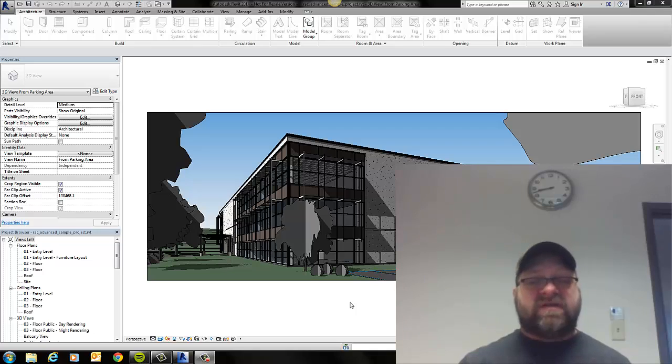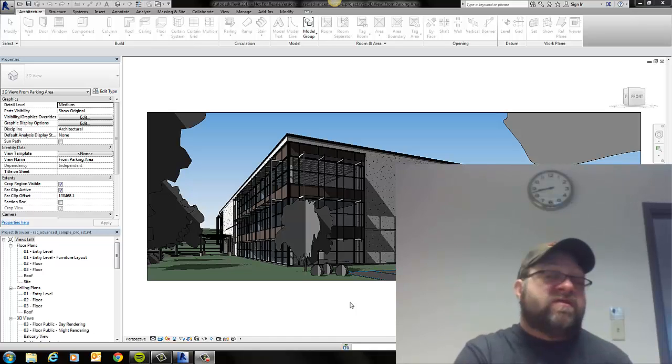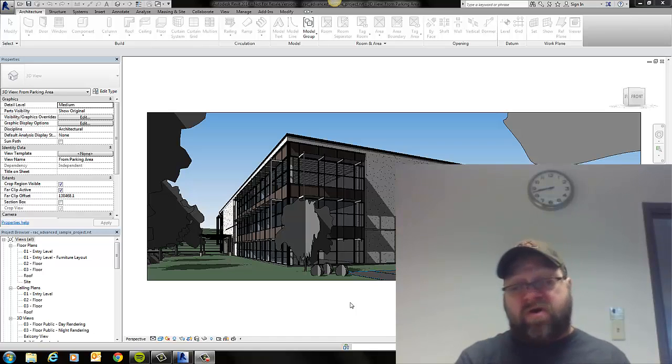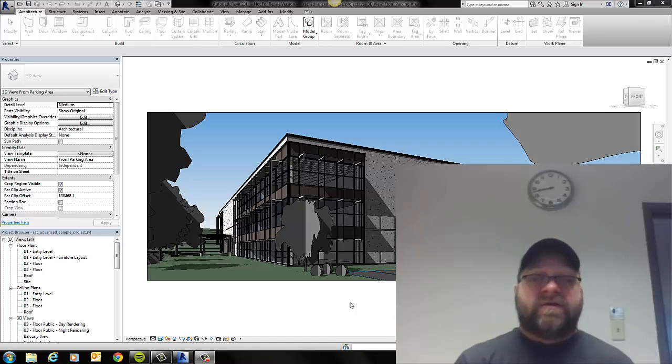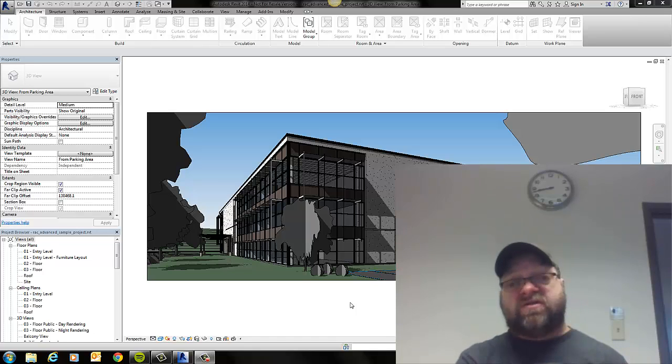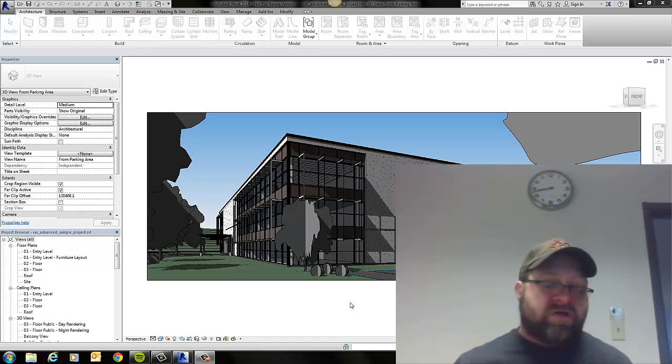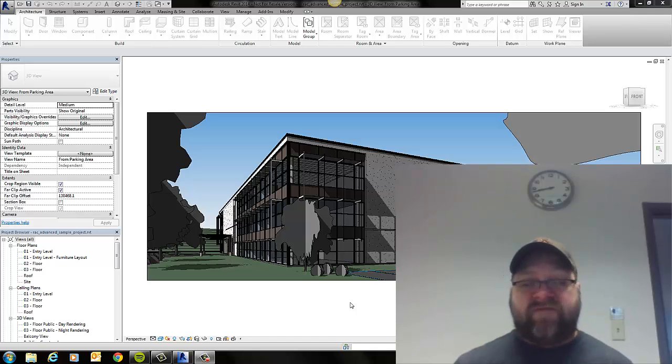So Revit takes a different approach, right? We've been working with it now for a few weeks, and so you've noticed I haven't ever talked about layers. Revit really doesn't have a layer system per se. It has something like it. It has a different organization system, but we don't call it layers. In Revit, it's part of that hierarchy of items that I've talked about a few times in class. Right at the very top, we have category. The categories of your objects are really what the organizational system is for all of our information.